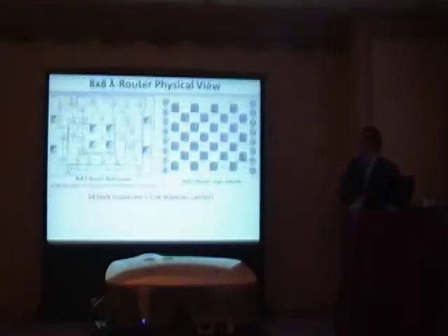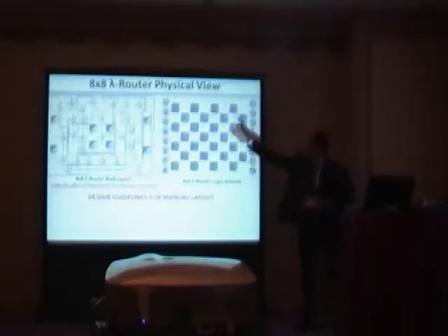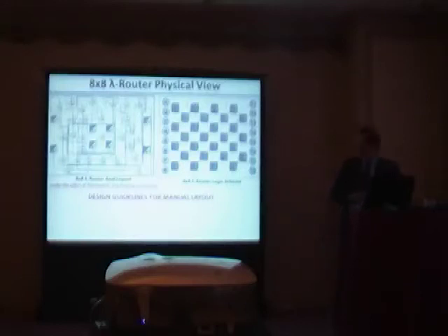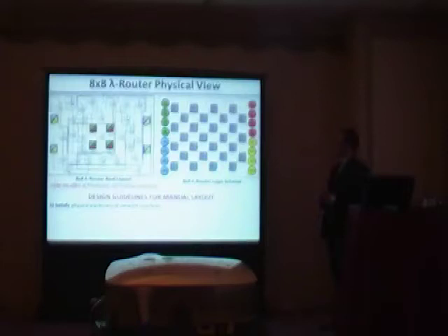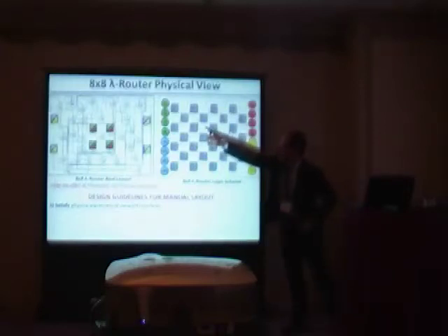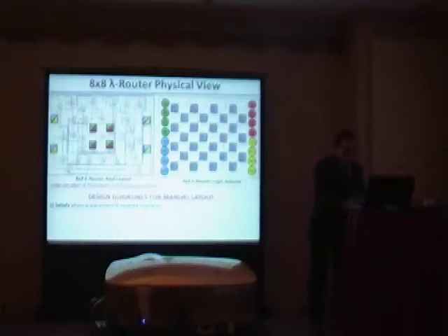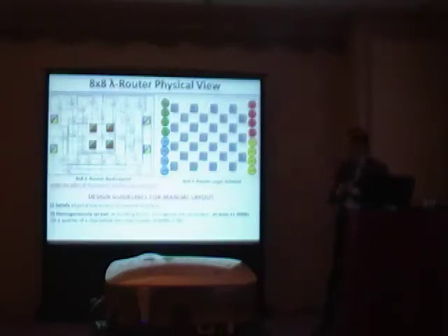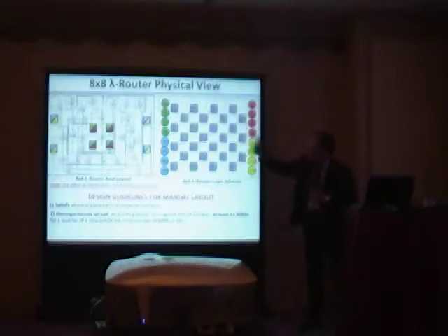In fact, when you translate this logic scheme into its physical implementation under the effect of the placement-related constraints, the situation changes. The design guidelines used in our work for manual layout are the following. Firstly, we satisfy our placement constraints, and then the position of hubs and memory controllers too. Secondly, we homogeneously spread all building blocks, all filters, in order to use as well as possible all the two-dimensional space. Notice that at every slice of the layer, we have at least 11 micro-resonators, where the total number is instead 56.